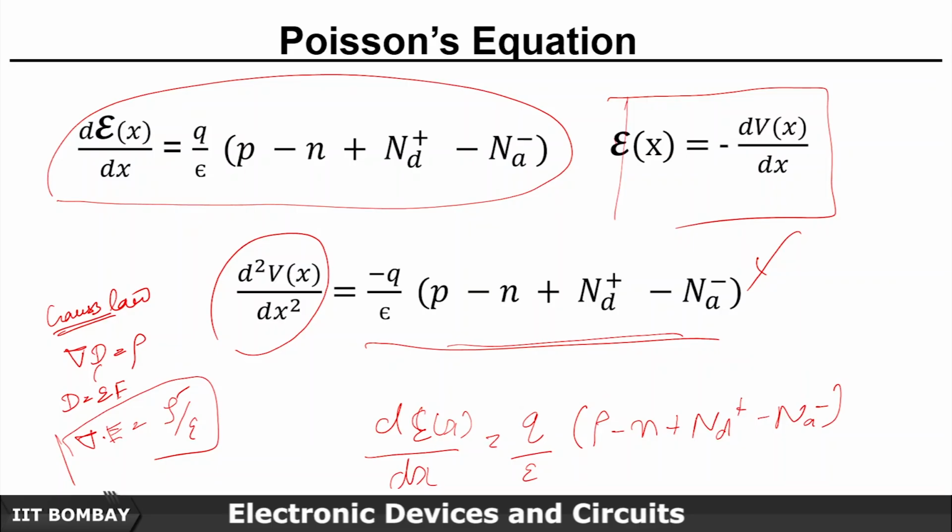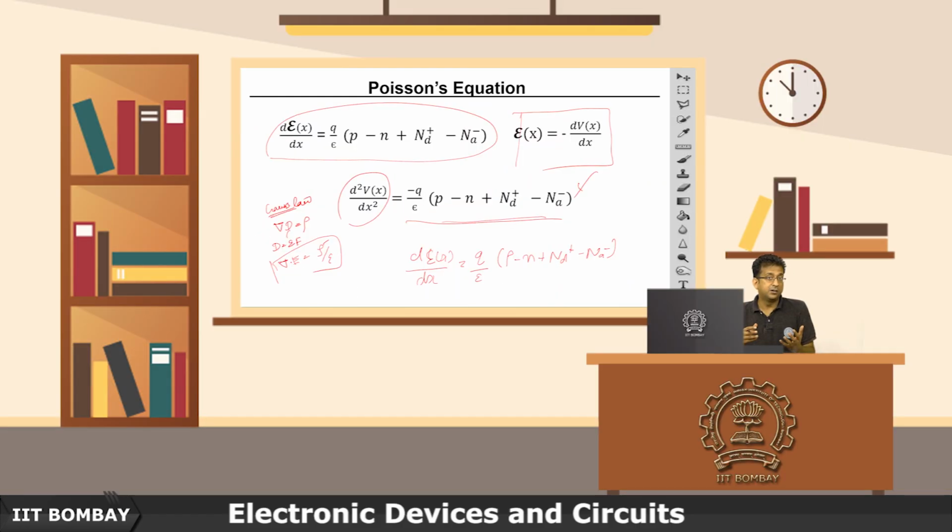So if I just summarize, today we talked about the diffusion of the charge carriers, why diffusion happens because of the concentration gradient, on what parameters it depends, the role of the diffusion coefficient, and the total current, a combination of the drift current and the diffusion current, and what will happen when there is thermal equilibrium, right? Drift and diffusion current will be 0, and an internal electric field will generate. In such circumstances the electron energy of the conduction band and the valence band will vary with respect to x, even intrinsic energy will vary, but the Fermi energy level will remain the same because there is no external field and equilibrium is maintained.